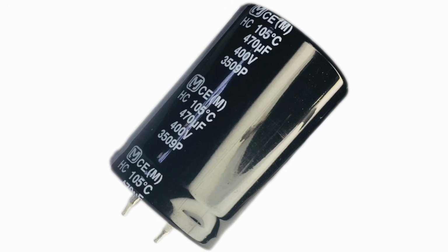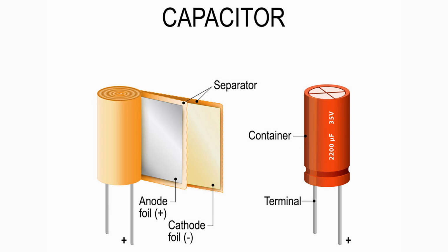The most common material type you'll see for these types of capacitors is going to be aluminum electrolytic, because they are what can offer you really high voltage ratings as well as really high capacitance values. One important thing to note about aluminum electrolytic capacitors is that they're actually polarized, meaning they have a positive and negative terminal which need to be wired properly in order to work.